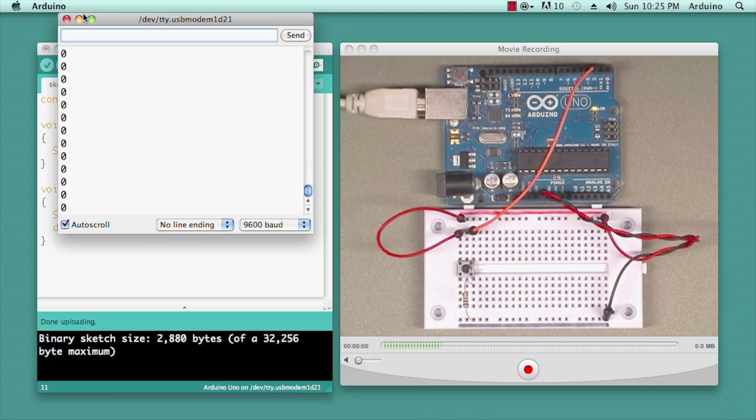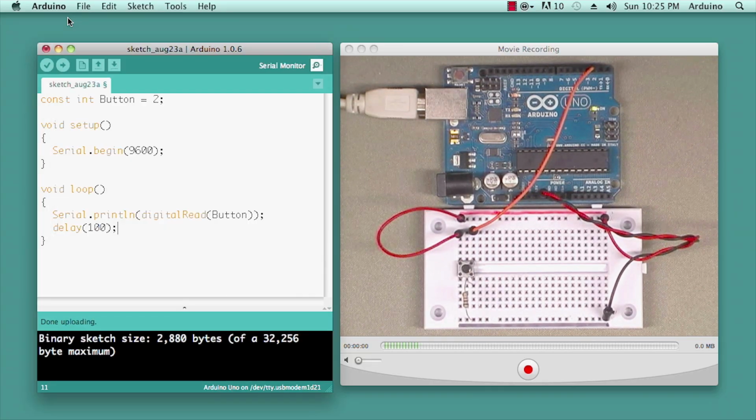I'll go ahead and make a couple little changes to the program while we're looking at it, just to do it a bit more like the way we would actually do it. We are just printing out the read of the button, but in a typical program, you're going to want to do something with that information. So instead of just calling the function here and then not having its value later on down in the program or in another subfunction or whatever, we want to store it.